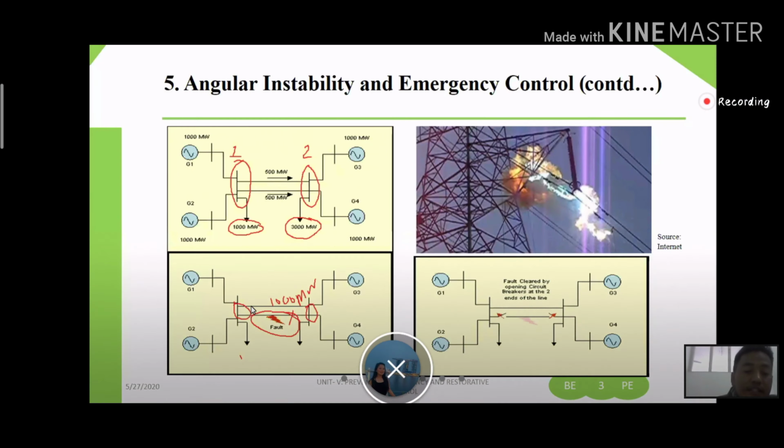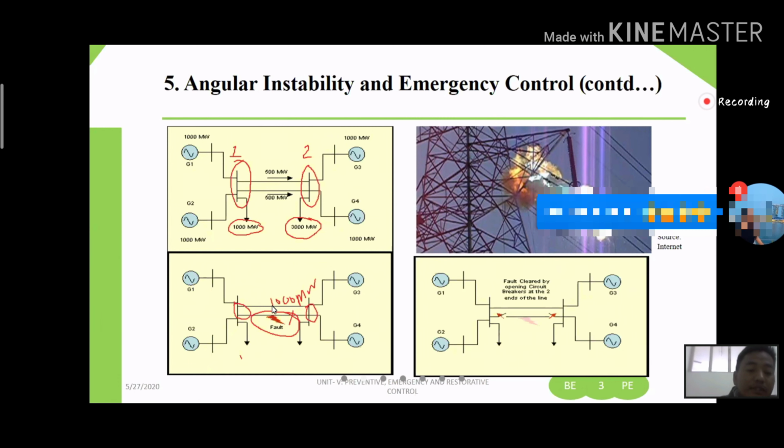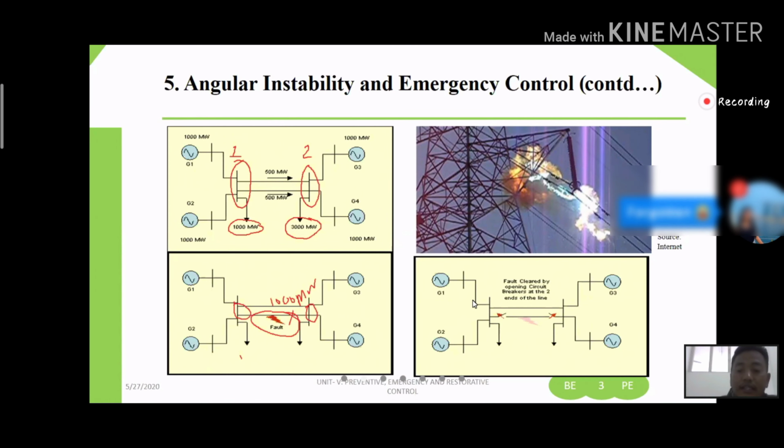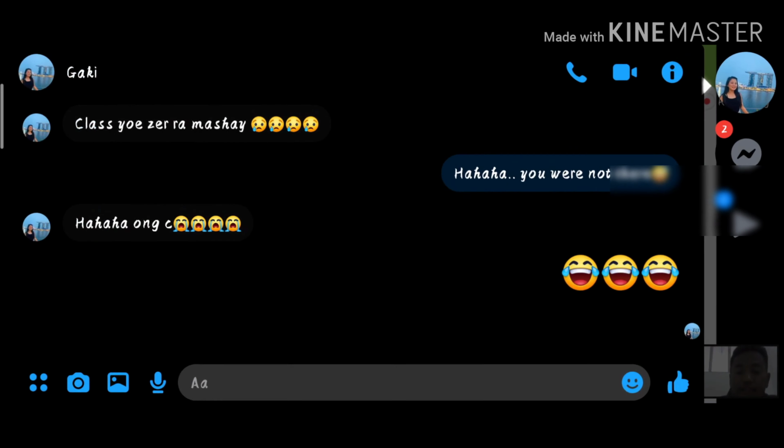If we see carefully, no equipment limit is violated, because each line can carry 1500 megawatt, but here it is carrying 1000, and this is how the demand will be fulfilled. So this is scenario one we have created.